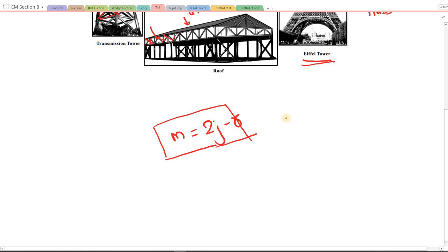Why are we studying truss here? In engineering mechanics, in truss, we will be looking at what sort of load is put upon the truss and what the behavior of the various members will be when the truss is loaded. Initially we said in the definition of truss that truss is a two-force member. Therefore a pair of forces will act on the member, and the two forces will be either tension force or compression force.